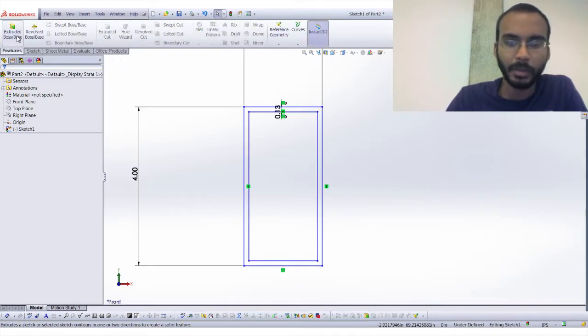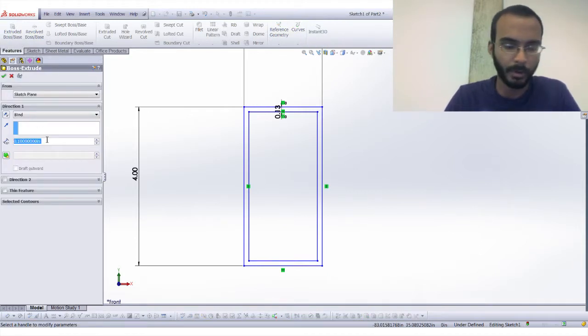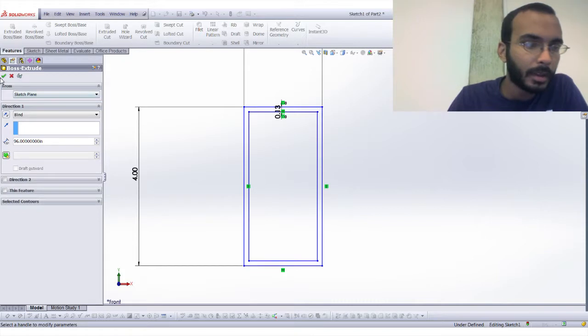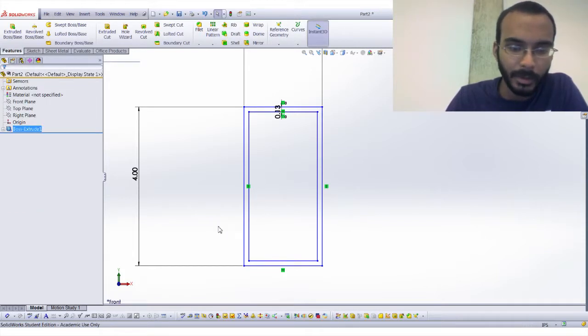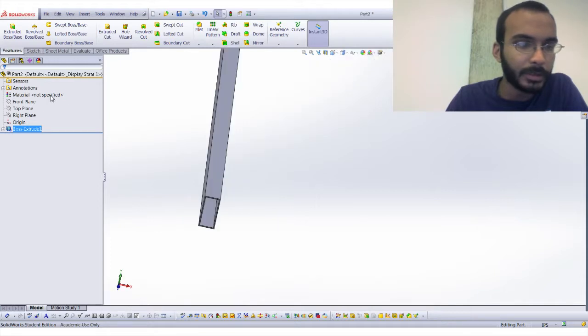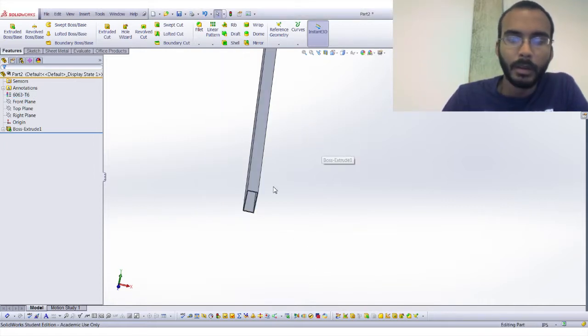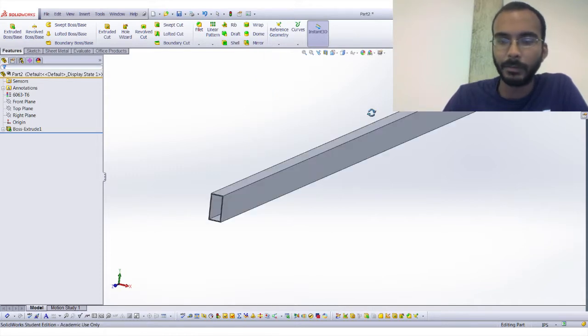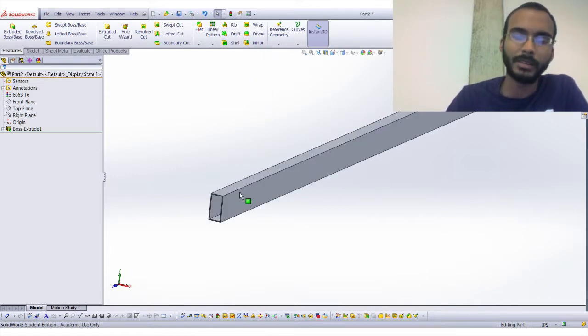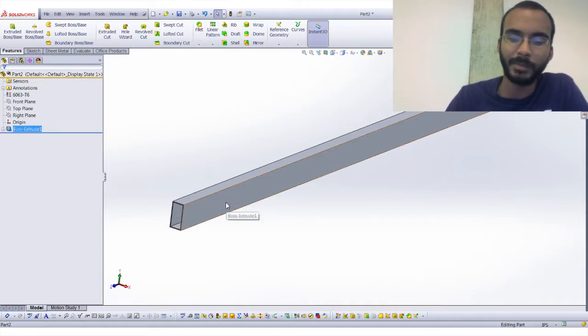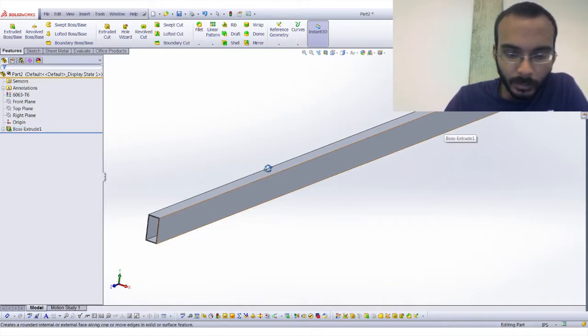And then if we wanted to make it actually apart, when we go to extrude it, we could tell it we wanted 8 feet of it, and it would do that. So now we have a nice big 2 by 4 piece of whatever. We can then set its material if we want. You can come in here and tell it whatever it is, which would be 6063 maybe, why not? And now this is actually basically a full part. You could go to Home Depot and buy this. Well, maybe not 2 by 4, it's a little big. You could go to some metal distributor and buy this. And this would be basically the exact same part you would get from them.